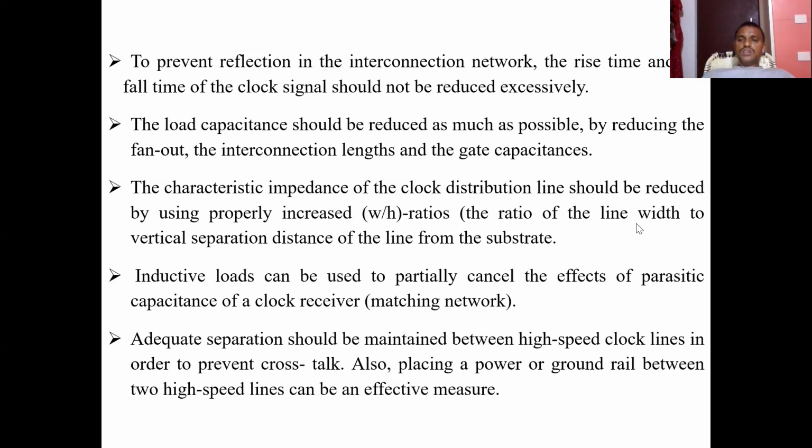Next, inductive loads can be used to partially cancel the effects of parasitic capacitance of a clock receiver. We can also use inductive loads to avoid clock skew.